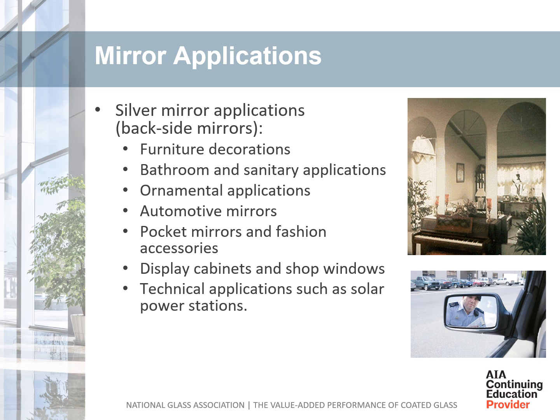Backside or second surface mirrors are produced using a wet coating process that employs mirror paint. The paint is applied as a wet film on the glass and then is dried in a furnace operation. Applications include interior and commercial mirror products, automotive and solar products like bent mirror reflectors.